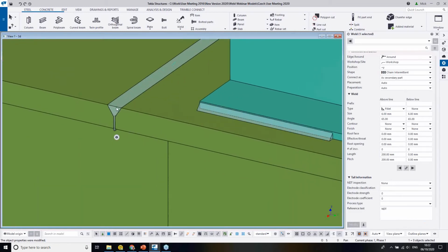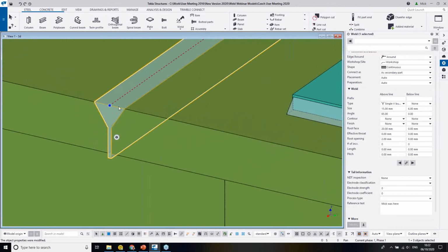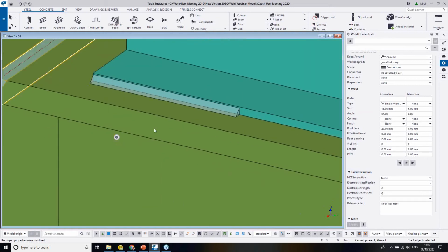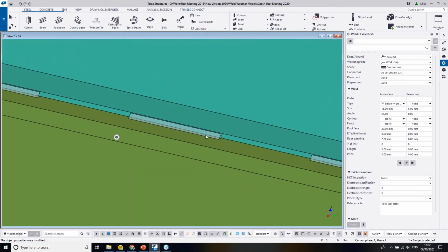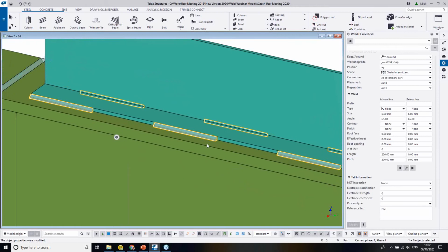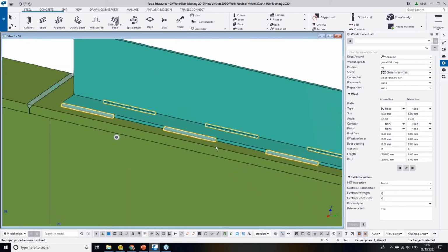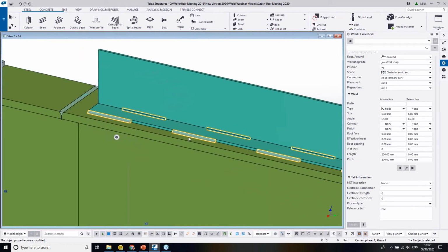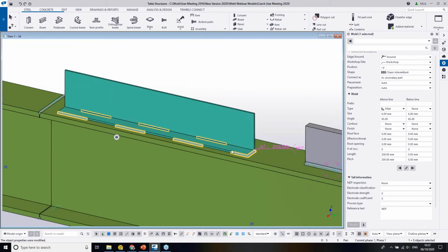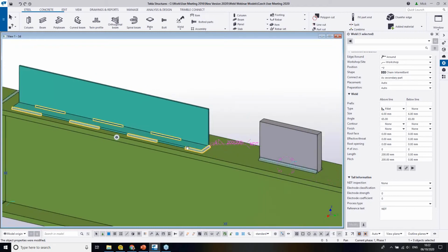So what I've done, let me just repeat this. I've put in here a standard sort of penetration weld where I've defined the root opening. The preparation of the parts is automatic. I've put in here the staggered welds where I can put in the chain of staggers, what the length is, what the type is. And this is all, again, so if I download that to a welding robot, it will just weld these parts exactly as I've defined them in the Tekla model.